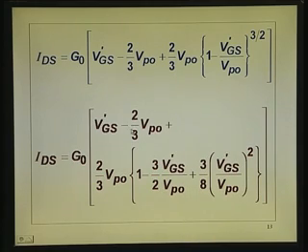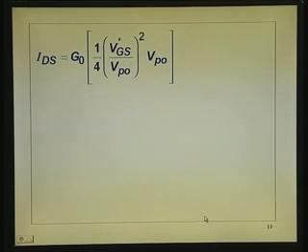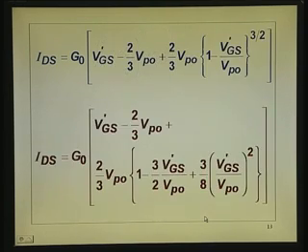That when you do, V_GS' minus 2/3 I am retaining, plus 2/3 V_P0 into 1 minus 3 by 2 times x, where x is V_GS' by V_P0, plus the square term, 3 by 8. Now you can see all the terms cancel out. V_GS' cancels, see these two terms cancel out. You will see all these terms cancel out and you are left with that quantity alone. So ultimately you have got that last term, everything else will go off.